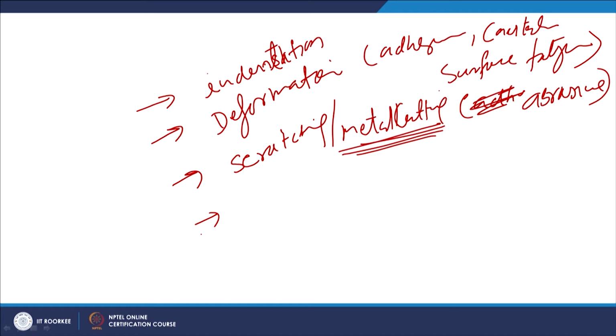It is also important to consider the hardness when we are choosing the counter surface. It is not good to have a counter surface of matching hardness values. It is always good if the mating components have different hardness. Similarly, hardness is especially important with regard to abrasive wear conditions.